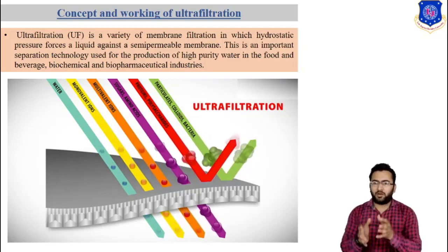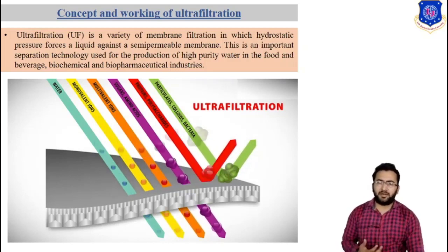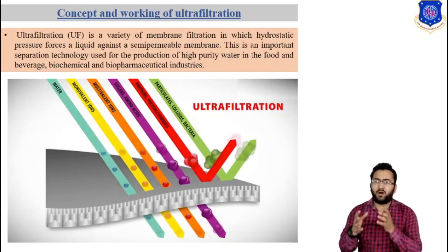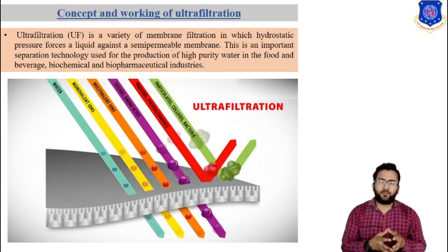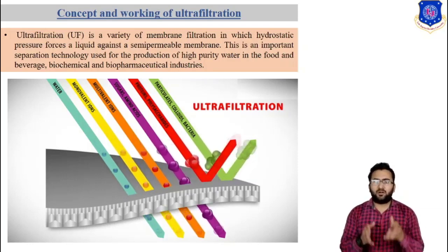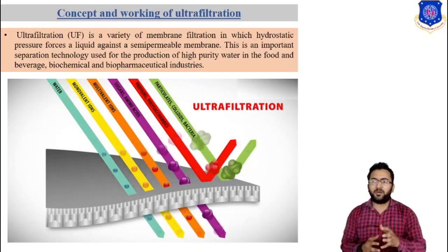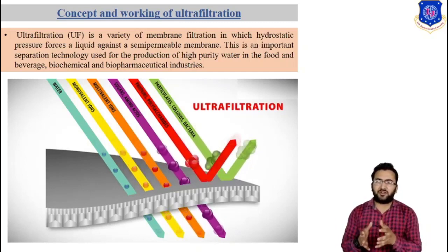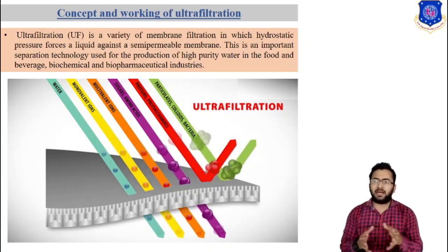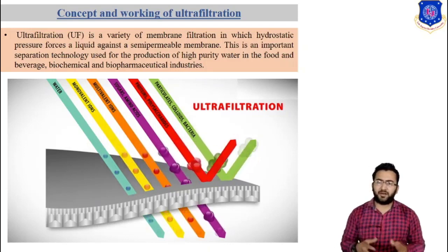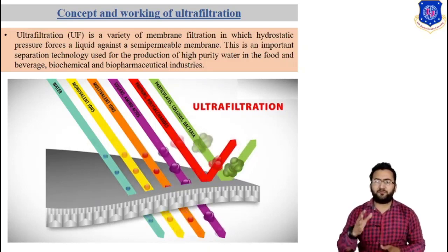However, the molecular weight cutoff method has some limitations, such as that many membrane materials adsorb protein in pores and also remove protein from the permeate by adsorption in addition to that removed by sieving. Therefore, membranes can be characterized only when they are clean. Ultrafiltration membranes have no sharp distribution of pore size.